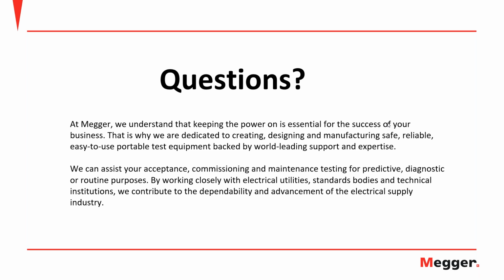From the gap values, I'm assuming this is a question related to 1816, and the recommendation is to start with the 2 millimeter, but if your oil does not break down, then you have to move down to the 1 millimeter. The typical voltage that the field instruments will go up to is 60 kilovolts or 70 kilovolts. Usually good oil, or oil that is recently processed or in a transformer, you expect to be in a very good condition.